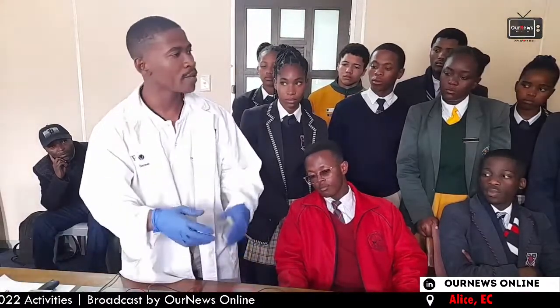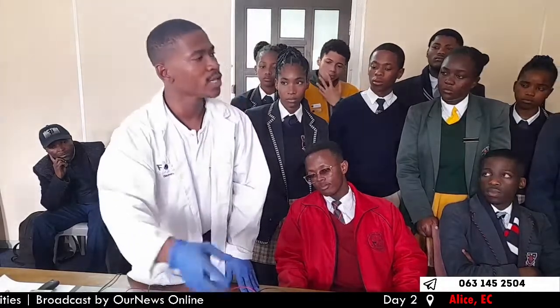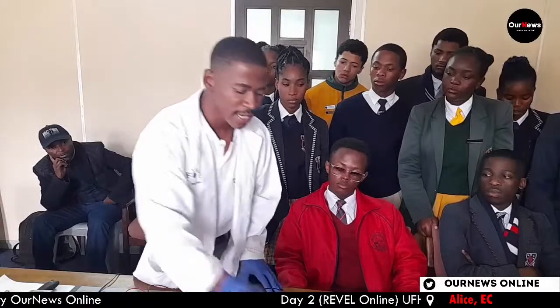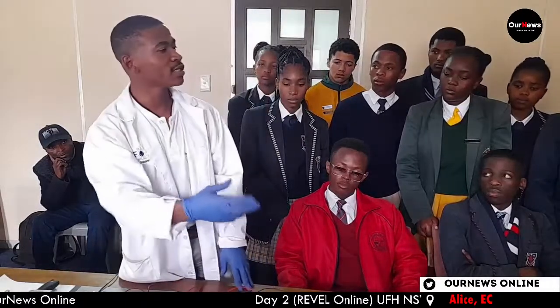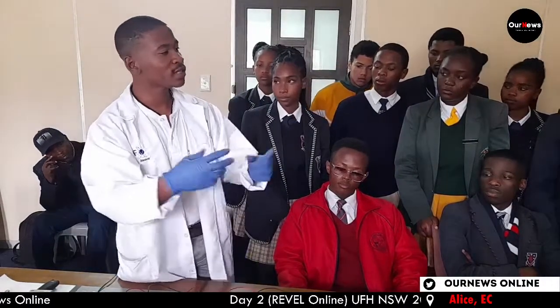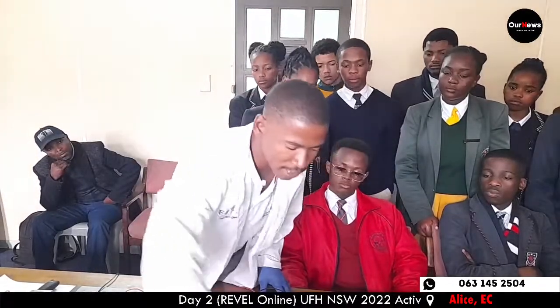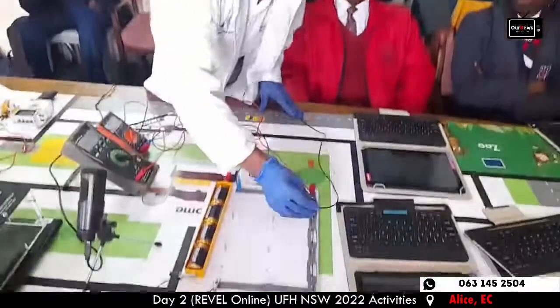That's the only thing it can do. So if it's more, it's a faulty battery. So now we have 5.06 volts. Moving from that, we want to check each resistor, how much voltage or potential difference it has. So I'm moving from this whole circuit, then I'm coming to this one.